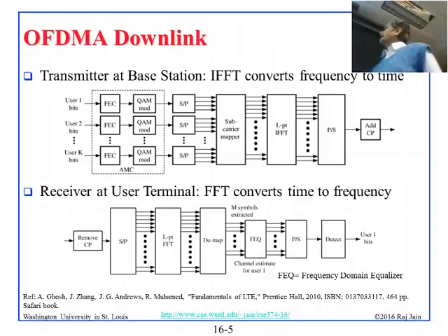Then it does the frequency equalization. This was not there on your slide. Frequency domain equalizer, FEQ. FEQ is the frequency domain equalizer. Basically, now you are going to do the demodulation, and you need to know what the channel was and so on. So for these carriers, whatever the amplitude and the phase was, we do that equalization.